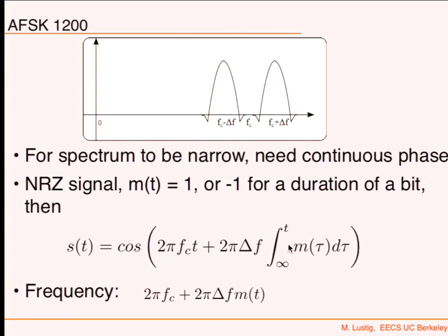I think it's a poor choice, because you use it, the detection then cannot be coherent with each bit. So what you're going to see is we're going to demodulate non-coherently. We're going to ignore the phase when we do the demodulation. We're going to demodulate by a cosine and a sine, or effectively by e to the 2 pi j, and then look at the magnitude of the result. And that costs you a little bit in signal to noise too, because you cannot separate whatever is demodulated to the sine, which will have some noise, and the cosine, which will have some noise. So that's what it is.